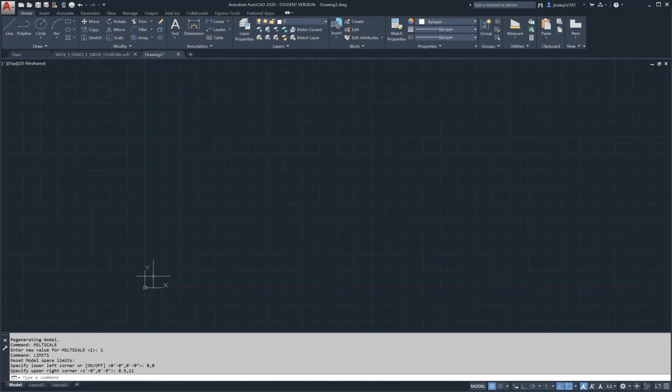If you remember from last week, the reason why we can't see them is because AutoCAD is currently displaying the grid everywhere. What we need to do is change it so that AutoCAD only shows the grid inside the limits. The way that we do that is, if you go down to the bottom, we have our grid button, which toggles the grid on and off. If you go to the right, there's an arrow, and when we click that arrow, we have access to the snap settings.